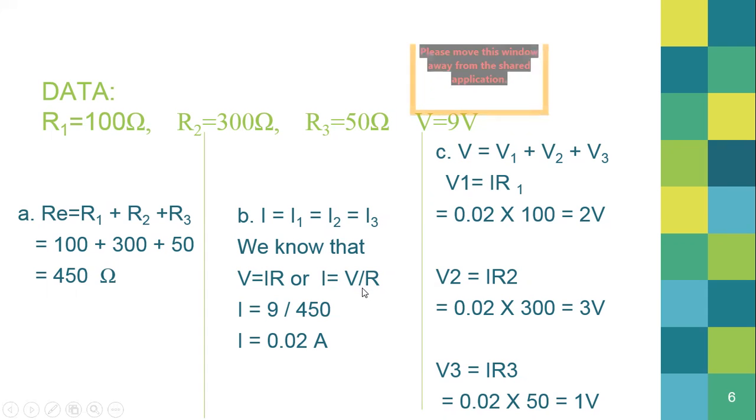Here we are using the total voltage of the battery and the total, or equivalent, resistance of the resistors, not R1, R2, R3, because we have to find the current of the battery. All the currents are the same in the series combination, so just find the one current, that is the current of the battery. In this case, use the total resistance.